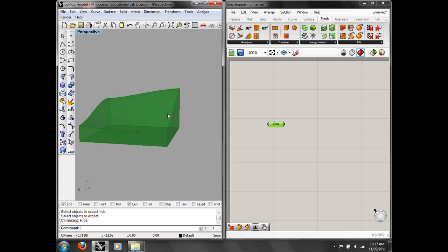And then I'm going to put a label right in the center of each of those. And I could put the two things on two different layers when I bake them. So one layer is cut, and that's going to cut the outside, and one layer is score, and that's going to be the label part, right? So I'm going to have the labels parametrically. And then I can adjust the number of contours I take, and it's going to instantly create that cut sheet for me. Okay? Let's see if it works.